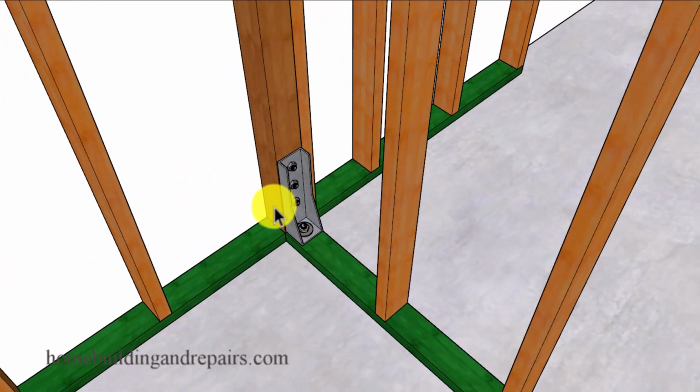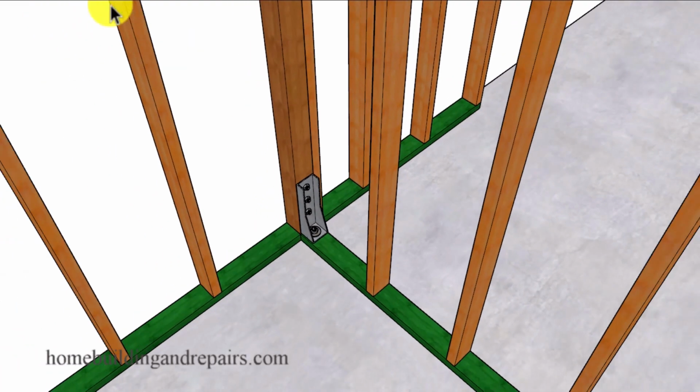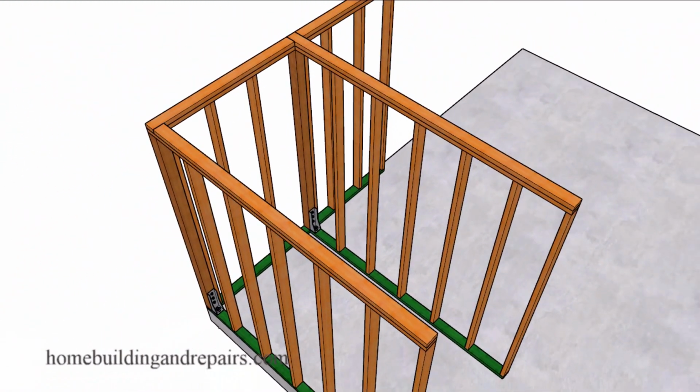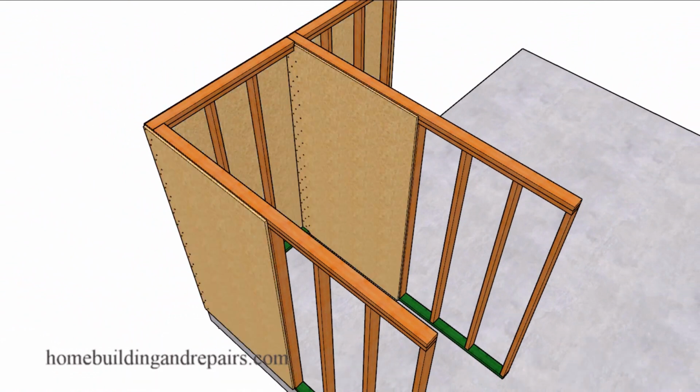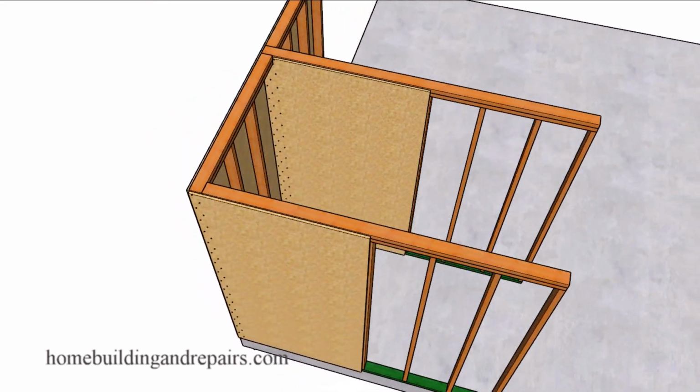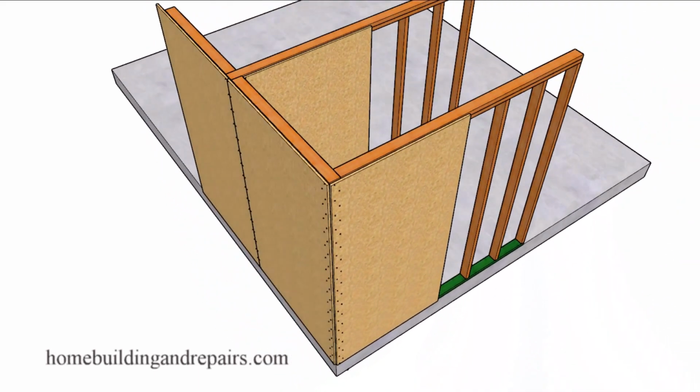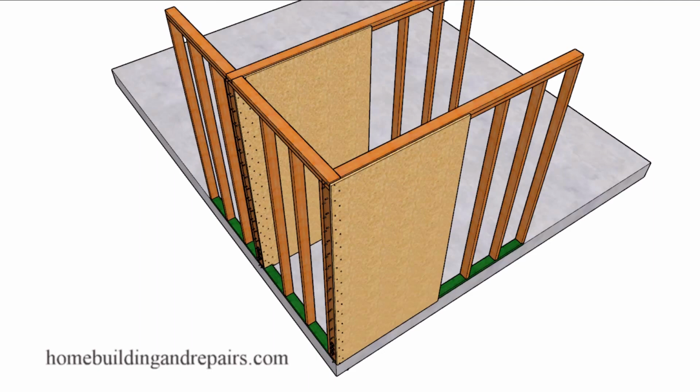If this one here is not located here, it's over here, then you might want to point it out to the structural engineer to see if they want to move it. If not, locate it where the structural engineer on record for your building plans has it located, because most engineers aren't going to want to go back and do any modifications without getting paid for it if they've already been approved by the local building department.